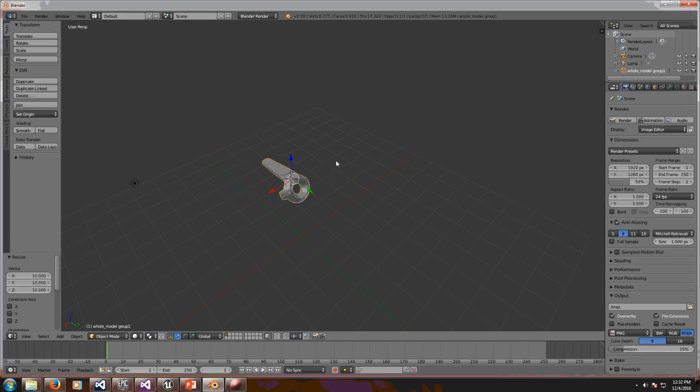So I'm gonna hit R on the keyboard, and if you make a mistake at any time, you can push escape and then Control Z if it actually went through. So I don't want, for example, to do any form of this rotation. So I hit escape. I'm gonna push R and Z 90 degrees. Actually escape. I want R, Z minus 90 degrees. So now you see that the controller is facing the X direction.